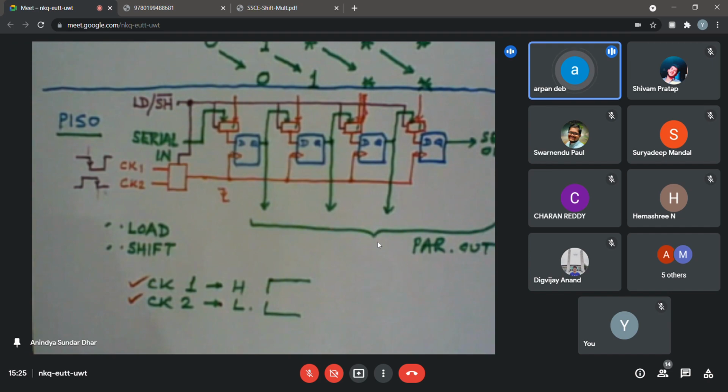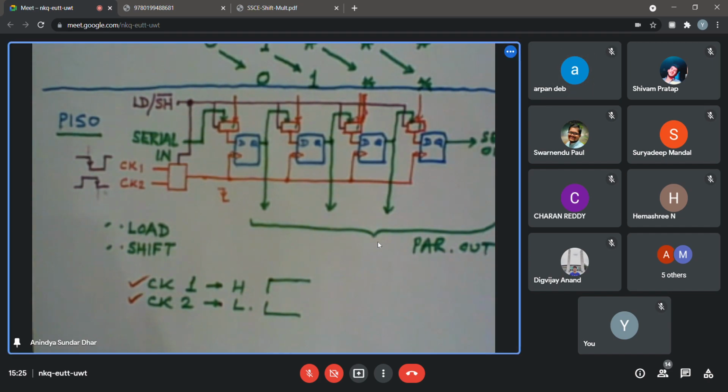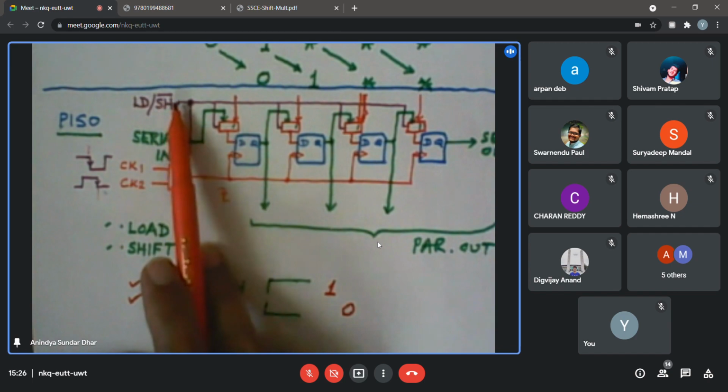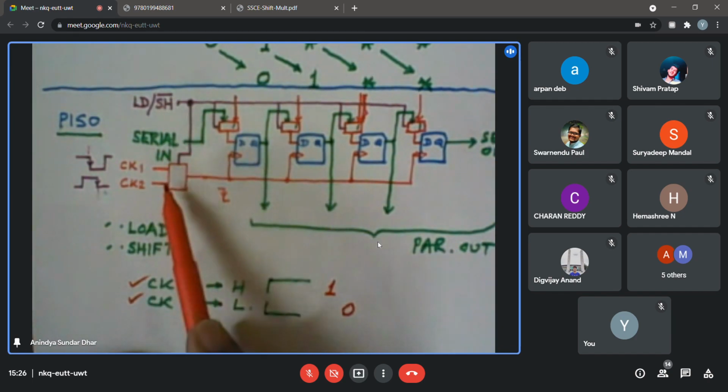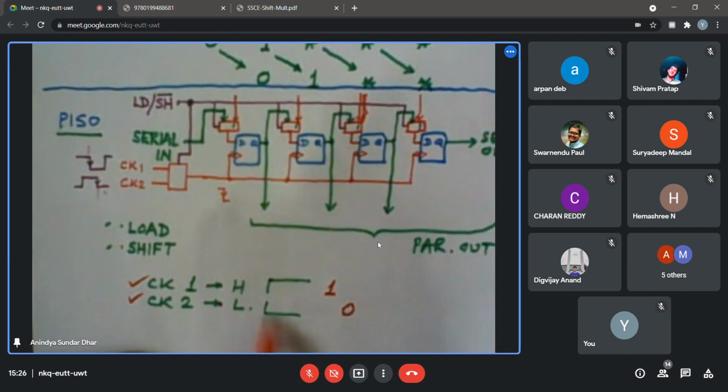So the flip-flop will face a falling edge. I could not make out, I think two of you are probably saying it simultaneously. Krishnan, can you come again and say? It will think that there is a falling edge there, because originally it was high, and as soon as I choose clock 2, it will become low. So when I shift the load or shift signal from clock 1 to clock 2, because one was steady high and another steady low, it will certainly generate a falling edge.